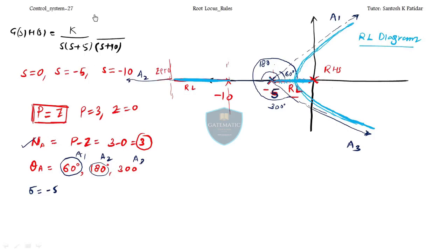Suppose instead of this, the scenario is like this. These are all the zeros. In the numerator, all these points are given. So here you have -10 is 0, this one is 0, this one is 0. The RL branches will be the same as it is. Now, the poles will be at infinity. Now, these root locus branches will come to the 0.